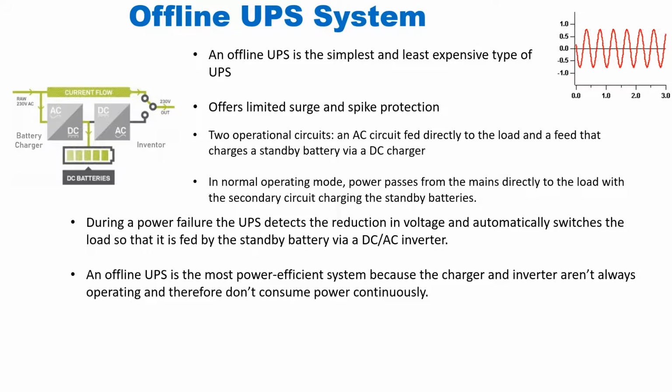It could be that the inverter circuitry is broken, or has a fault in it, but because the utility company is providing clean power, that inverter circuit is not activated. So you don't even know if there is an issue with the inverter circuit.